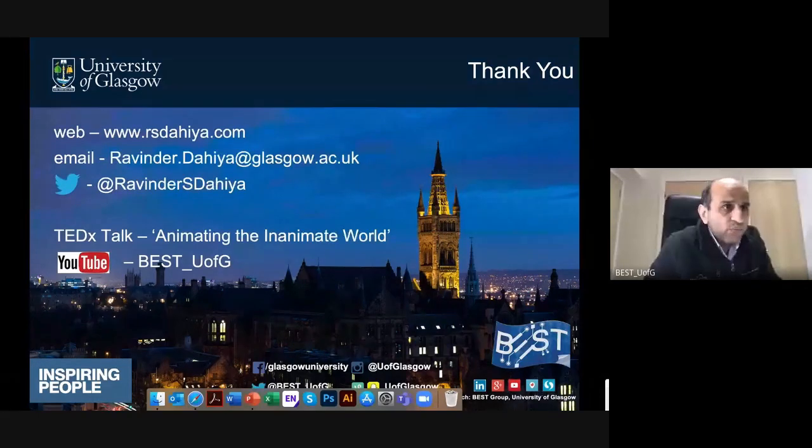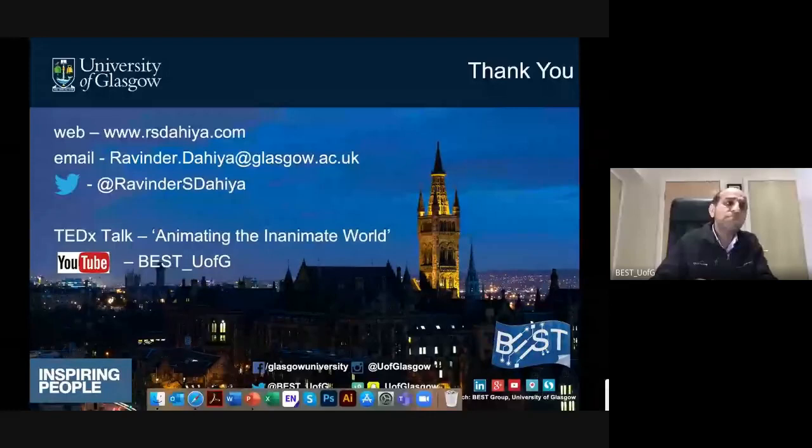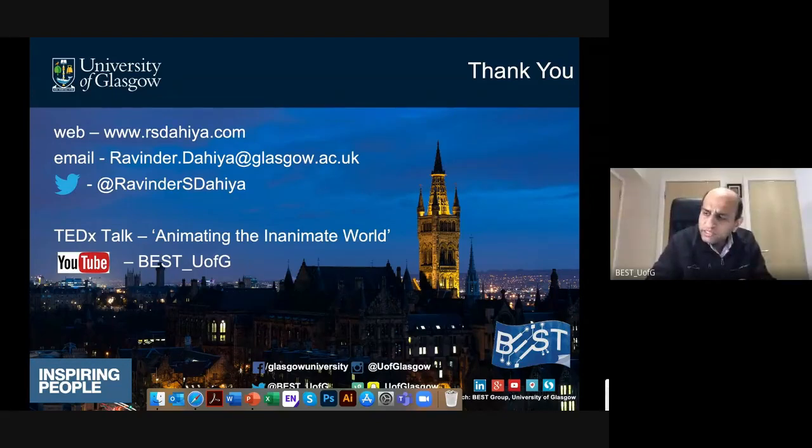Then there is a question: what is the typical power requirement for a flexible device? Have you used piezoelectric energy harvesting technique to power the device? As far as the power requirements are concerned, currently we have not really looked at that aspect when I see the electronics, but the goal remains that it should be low power. The sensor part we have been more careful about in terms of power. We have used graphene-based capacitive sensors, for example, which require as low as 20 nanowatt per centimeter square.